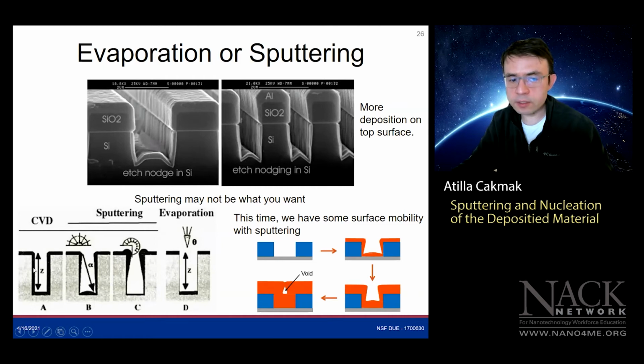So just look at the parts that I'm highlighting. There's a little more information that you can find in the supplemental. I'm just quickly going over these materials. You have some thickness here on the sidewalls, and you have some thickness at the bottom of the trench, right? They're almost equal to each other because this is driven by chemistry, surface chemistry, instead of ions coming down and landing on the surface. In the case of evaporation or sputtering, those were physically driven forces.